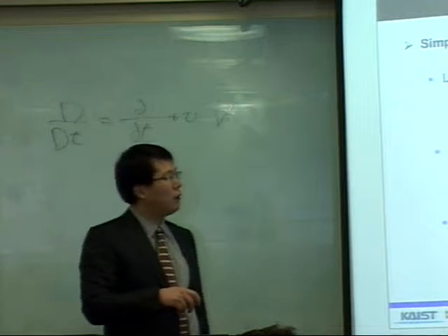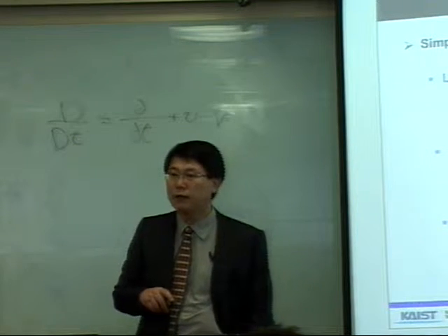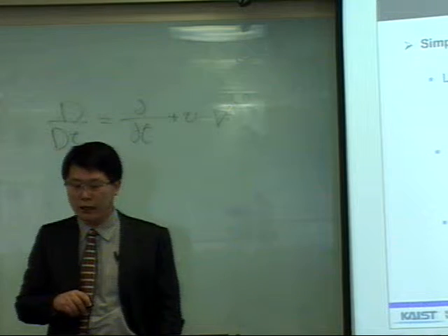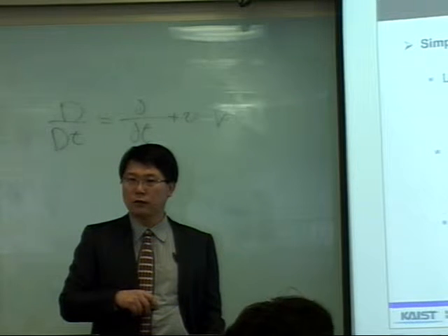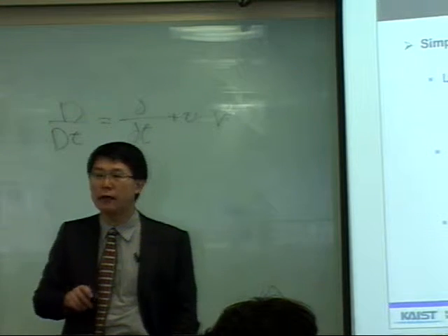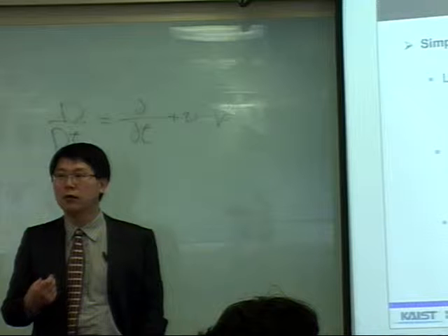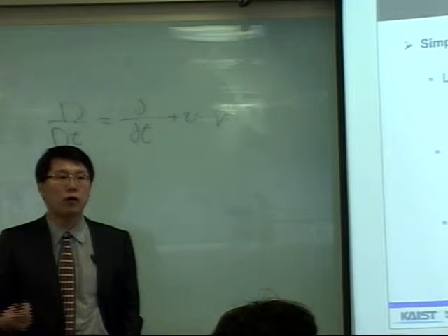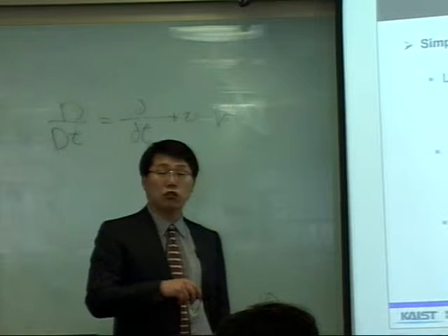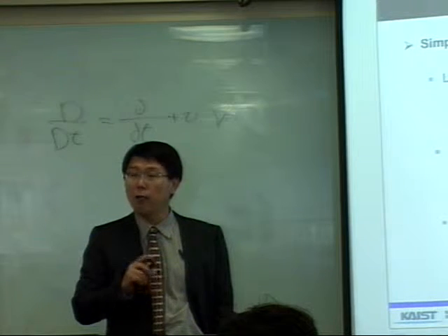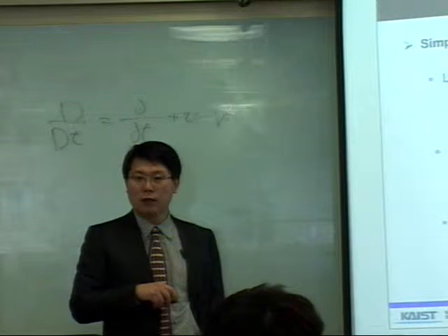You may be familiar with this equation. Rho Cp times the temperature change is equal to k times the Laplacian of temperature. What I wanted to stress is that this equation is just an approximation. We needed three or four assumptions to get this equation. This equation is only applicable to constant pressure fluid or solid.